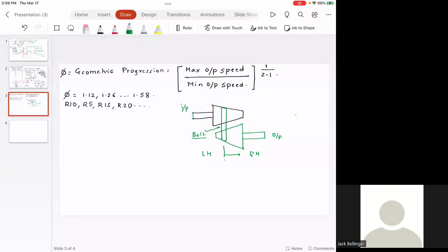But this reminds me, if you have a CVT transmission, there is its sort of brother, which is called a synchronous clutch. So I just have to tell you that as well. So this clutch is something like this. This is the clutch. This is input and this is output. If you look at this clutch, because of the conical shape, the engagement is not sudden. The engagement is gradual. This is used in the synchro mechanism. So that's why this is called a synchronous clutch.